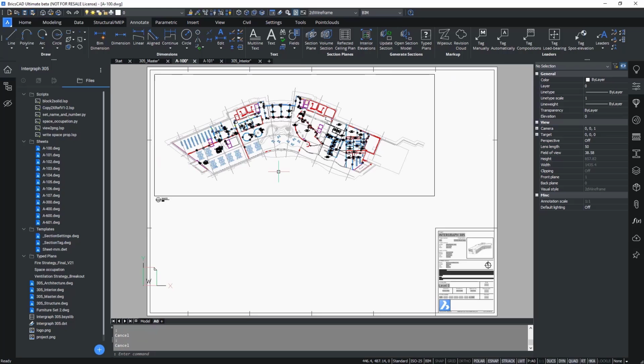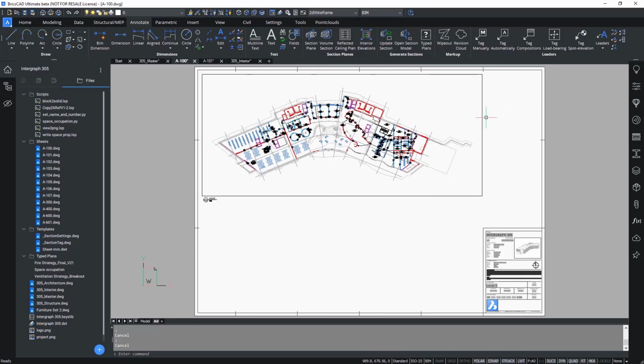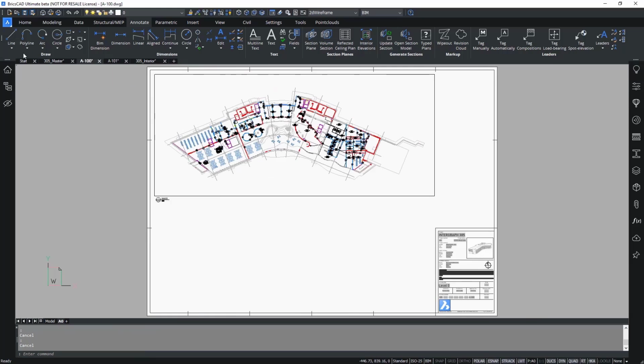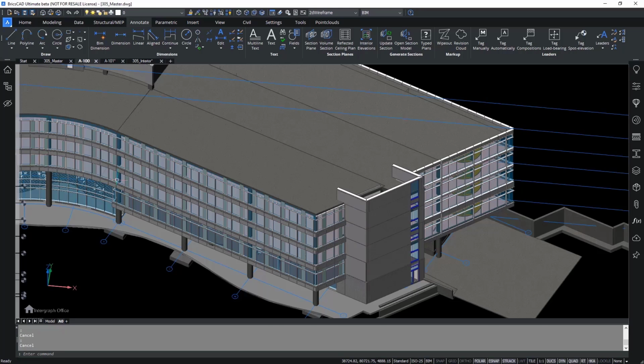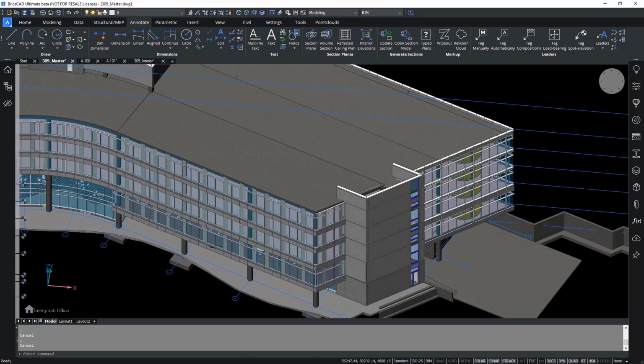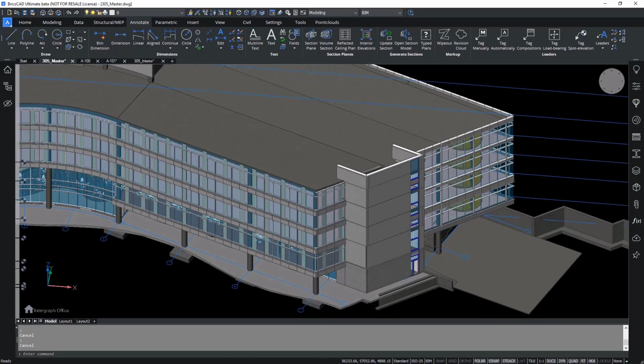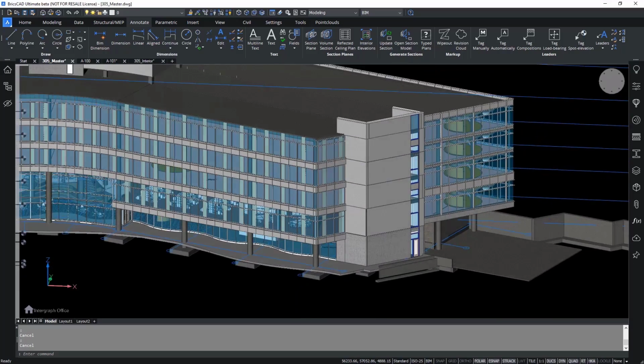So no construction documentation pack is left without looking into details or into a smaller scale drawing. V22 now supports default annotation graphics to help drawing production through the section indicator lines on paper space. Again, they exist as an mleader style in section tag.dwg, linked to the right entity via the XML file, just like how I demonstrated the number tag earlier.